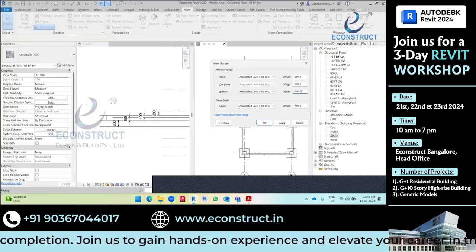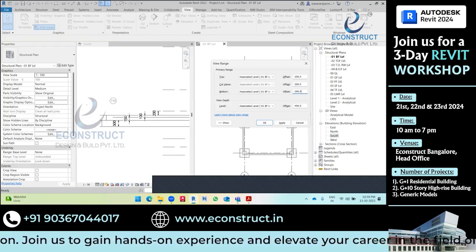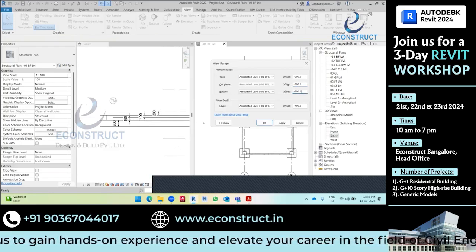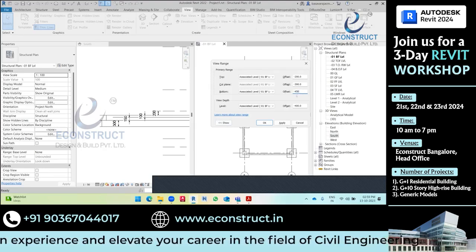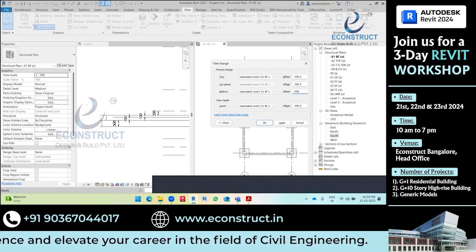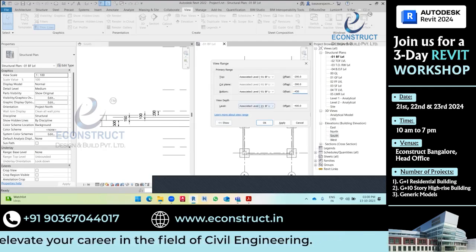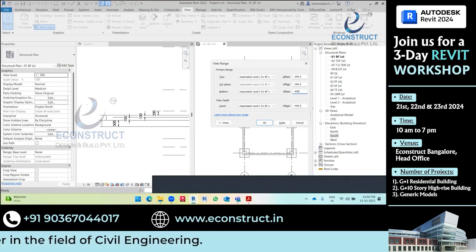And the bottom plane is 200 plus 100 plus 150, so it is minus 450. View depth from the basement floor level is 200, 100, 300 and 150, so minus 750. Okay, apply.